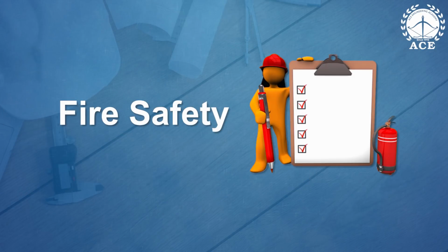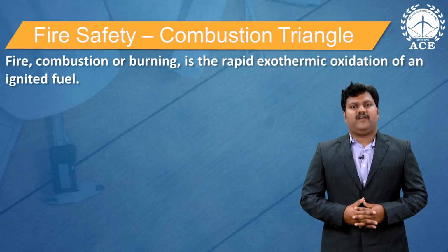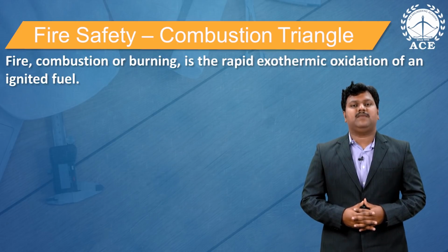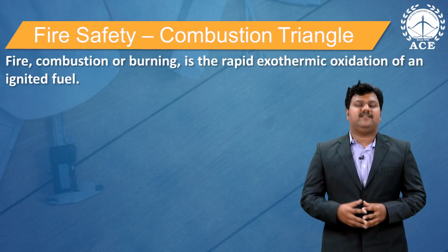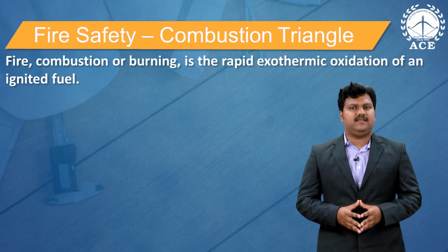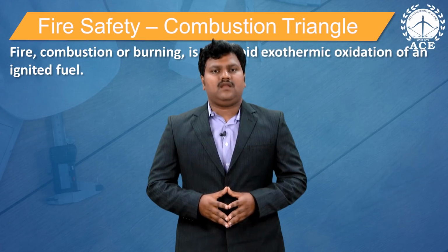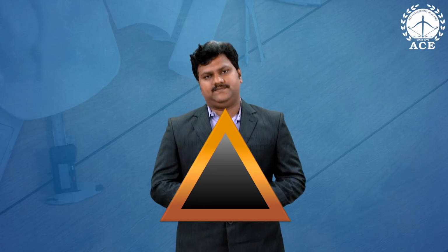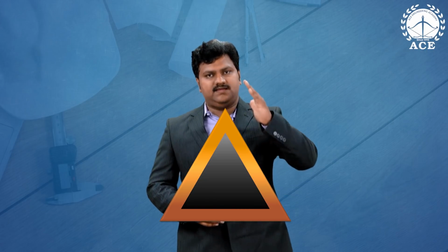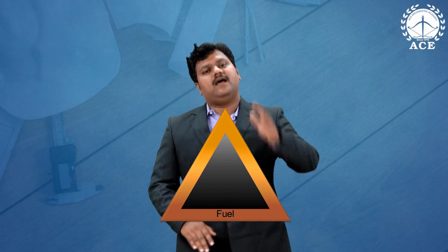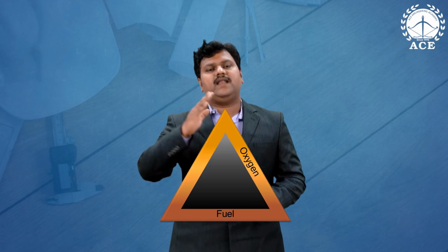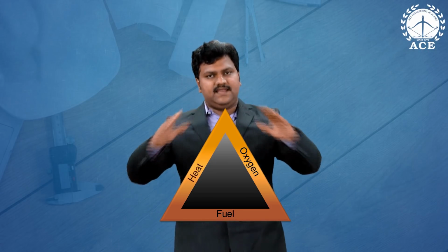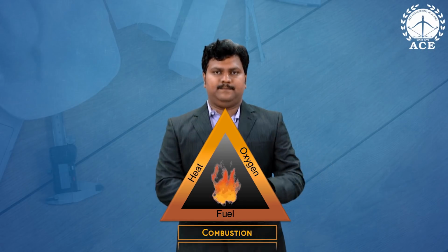The next topic is fire safety. Fire, combustion or burning is a rapid exothermic reaction, an oxidation of the ignited fuel. Now, if we take the situation of a fire, it requires three elements. That is, one is a fuel, the second is the oxidizer, and the third one is the ignition source. These three form a combustion triangle.